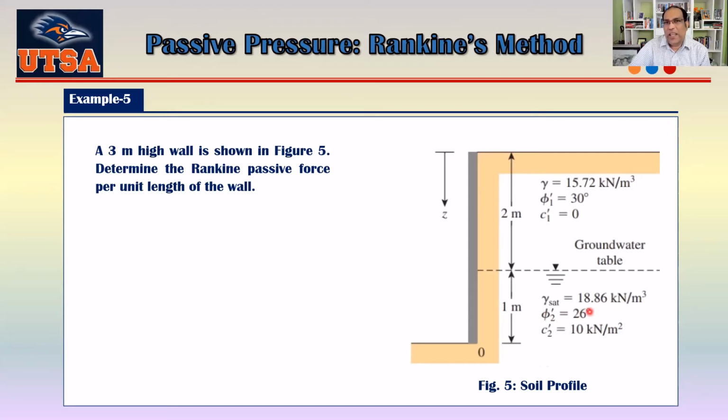They have like 20, 25, 30, something like that, but not 26. So if it is not given in the table, then you have to use the formula. It's troublesome to calculate that big equation every time, so it's always better to keep an Excel file, so that if you change the basic parameters, it will automatically calculate your coefficient.